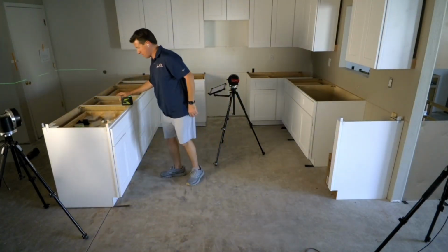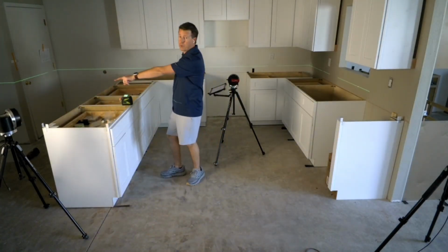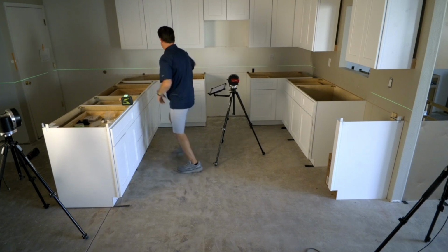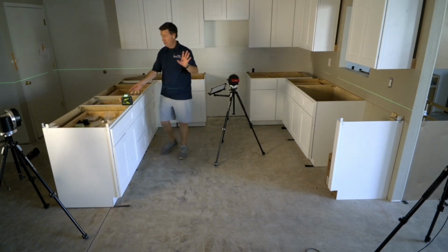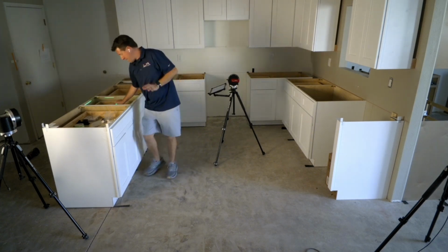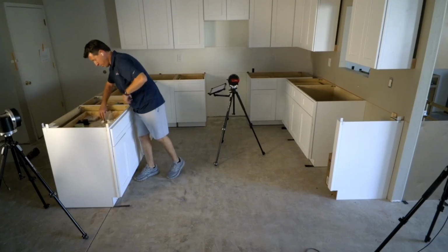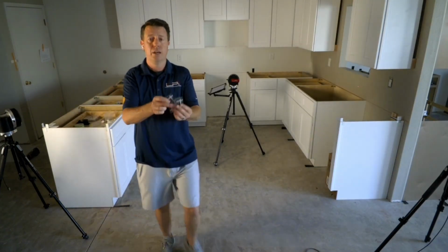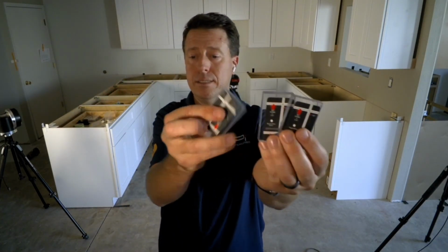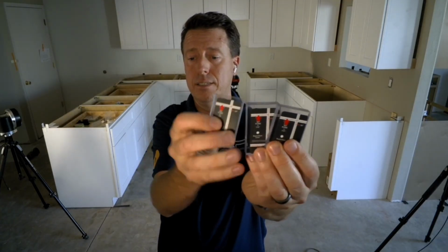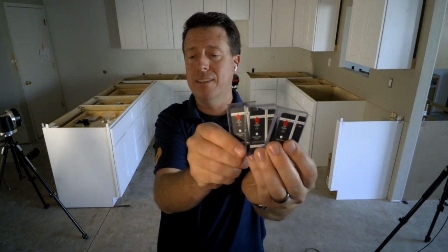Often I'd use a laser like this and shoot 3 points that represent that triangle in space, right on this green laser beam. But I'm going to start with our standard, simple way of capturing a plane. We'll take 3 of these blocks, and I want to make sure they're all the same height.